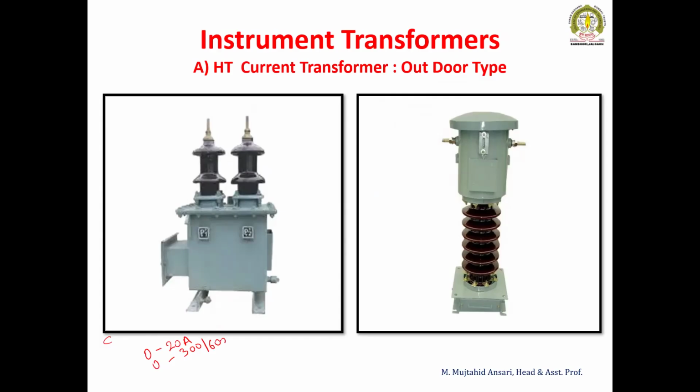But in practice, in the substation, the voltage level is 132 kV, 400 kV. Nowadays, in ultra high voltage, it is 765 kV even in India, and we are thinking towards 1200 kV. Some test lines have been laid out. If you are not able to measure the high voltage, it is necessary to extend the range of the existing voltmeter, ammeter and energy meter.